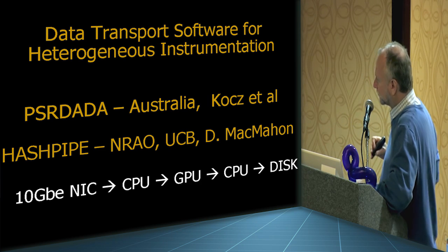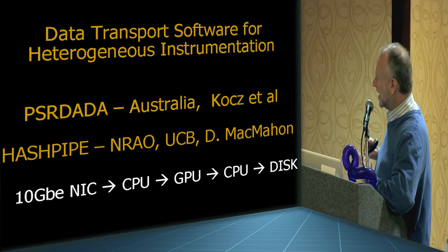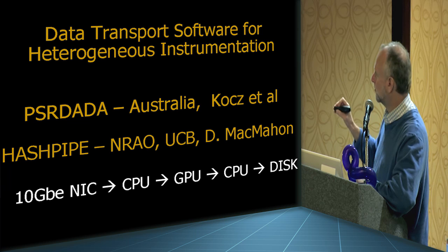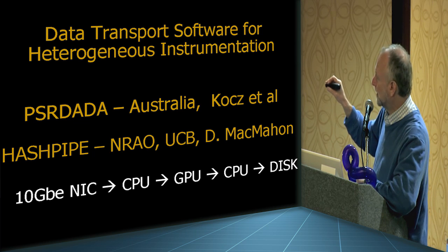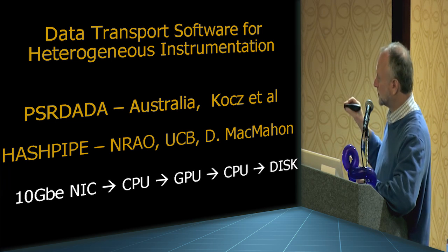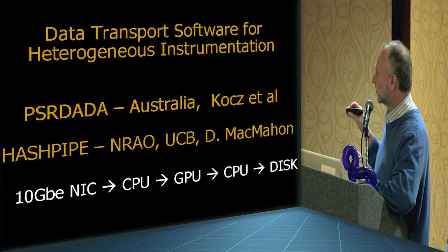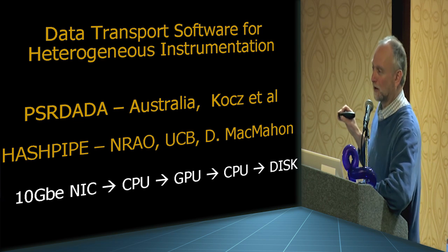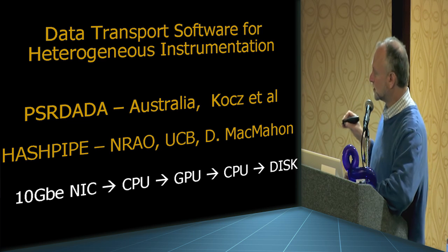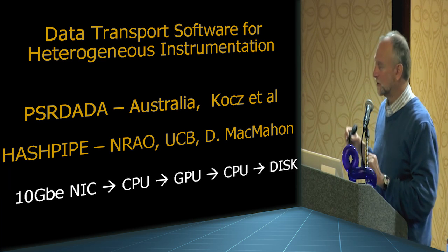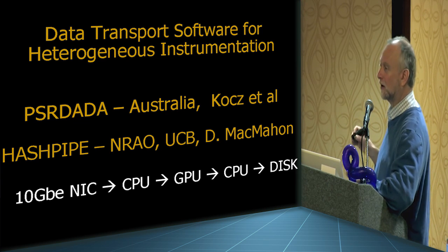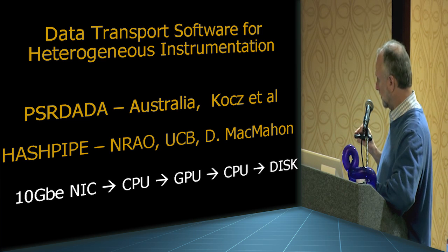We've also been working on the data transport codes to move high-speed data from NIC cards. I think I mentioned this before. We have this problem of getting data from a NIC through the CPU into the GPU and onto the disk. That took a lot of work. You'd think that's really simple, just moving data around. Maybe it would have been if you guys did it, but it took us a long time to figure out how to move this high-speed data around through all these circular buffers. We typically use computers with a couple of different PCI buses and dual socket machines, and we can get about maybe 40, 50 gigabits per second from the outside world into these GPUs doing that. We'd like to get more.